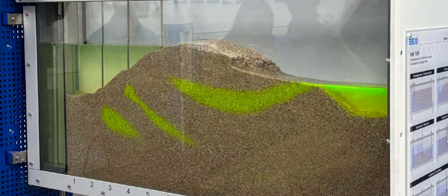Step-by-step experimental procedure. 1. Constructing the earth dam model. Dry packing. Thoroughly clean and dry the inside faces of the glass tank. Place the sand into the tank in uniform layers, 50 to 75 mm thick. Compaction. Lightly and evenly tamp each layer to avoid creating internal voids or artificial stratification, which would skew the flow lines.